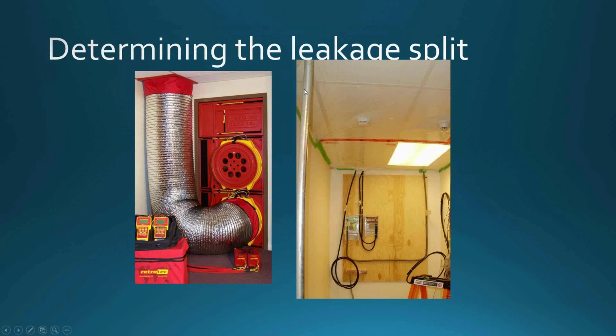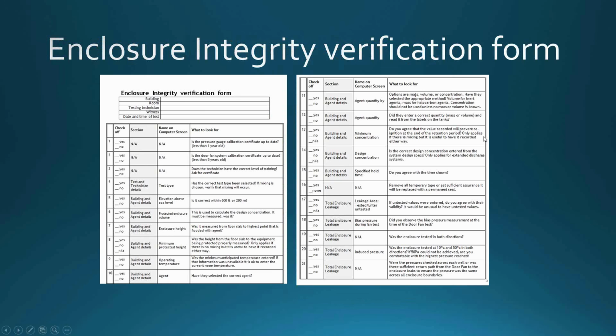There is a section in the standard in all of them that allow for both plastic on the ceiling, and the Flex Duct test is specifically named in the NFPA standard as the plastic on the ceiling test. So yes, it is allowed, and no, it's not cheating. And it's talked about more generally in the ISO standard, not done as often, but it is just as allowable. There's a section in there that allows for the measurement of the leakage split, or the F value.